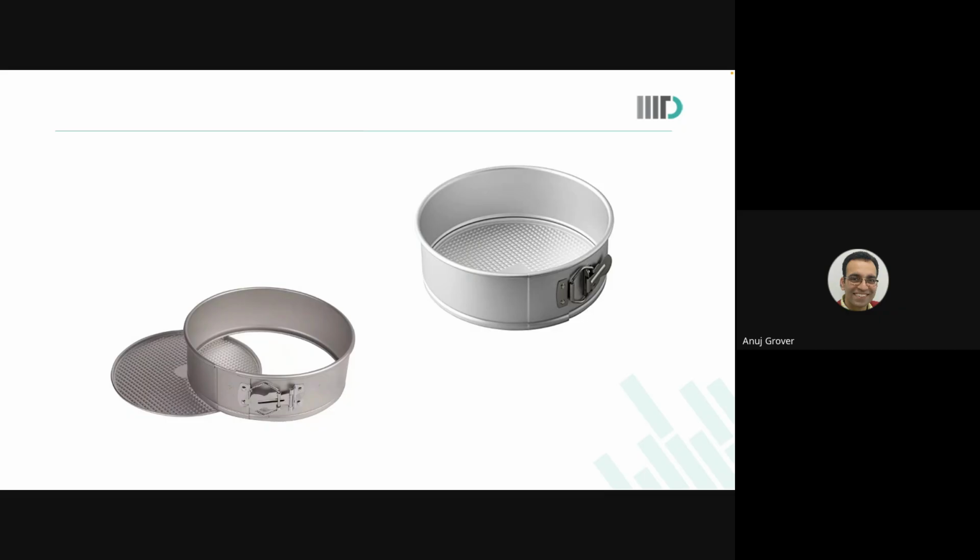And here what you really need to look at is, like what we did there, we changed the mold in such a way that the coolant would pass not linearly but in a curved route. Similarly, you may want to now redesign your baking machine to say that, okay, there is the most fear of cracks coming at the top, so the heating at the top will be done in this way. I will also blow air. I will also do something else so that my cracks do not even come. Are you with me?